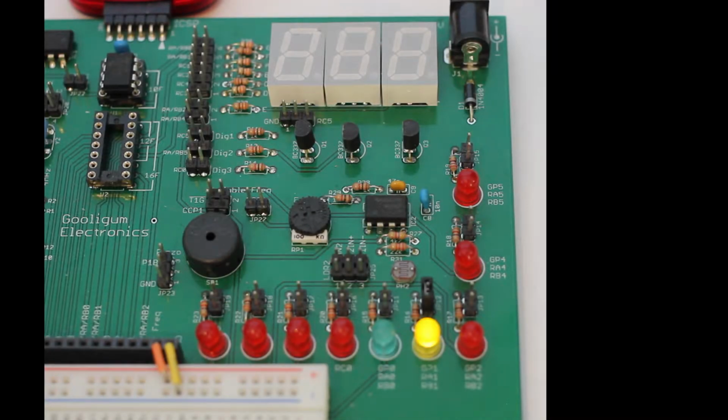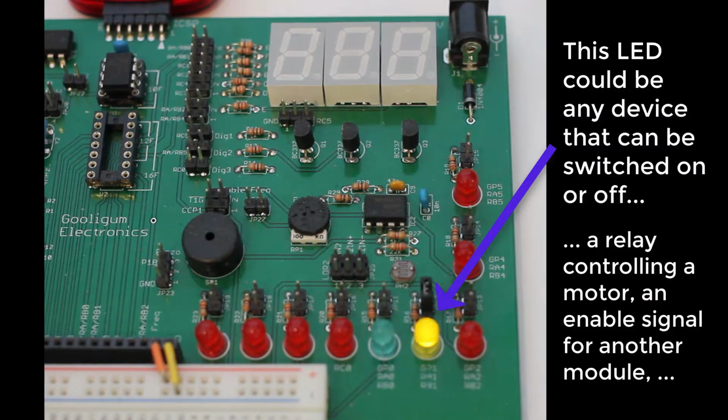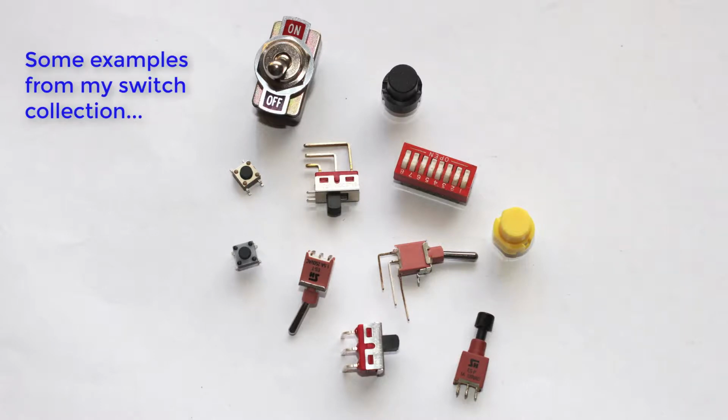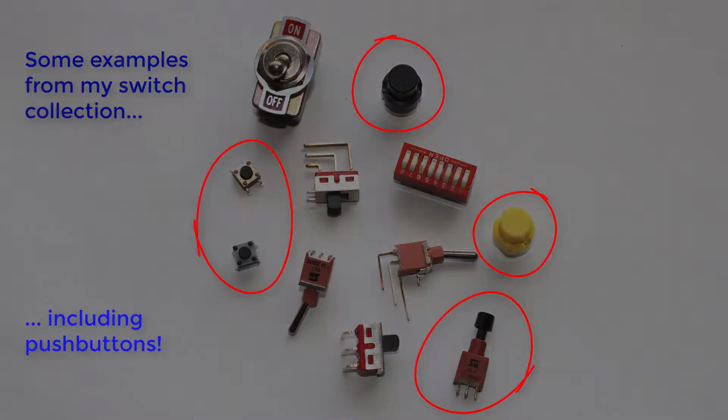In the last lesson, we were still blinking LEDs. Now that's more useful than it sounds because, with appropriate drive circuitry, you can replace that LED with any on-off device you want to control. But unless your device will just run a fixed output sequence, it's going to need to respond to inputs from the outside world. And the simplest type of input, which we'll look at in this lesson, are digital inputs, on or off, high or low. We'll use a simple push button switch, but it could be anything that indicates an on-off status.